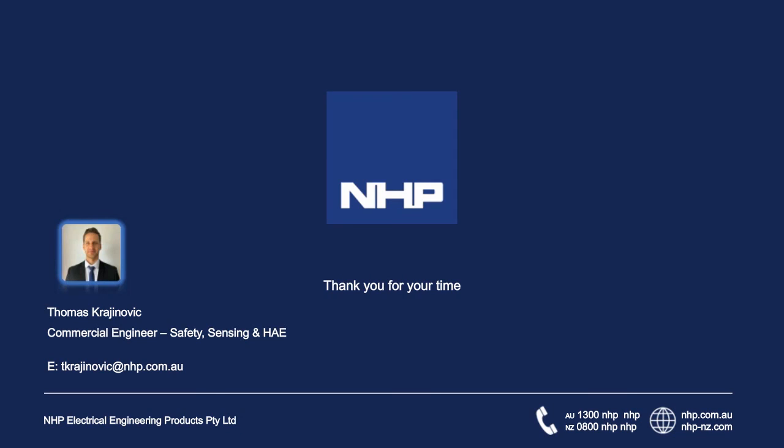Someone's asked, can I buy an unshielded sensor and block the sides so it works as a shielded sensor? What are your thoughts on that? Okay, so in that case, the answer is unfortunately no. So it's actually part of the sensor design internally, shielded versus unshielded. So placing metal on the sides of an unshielded sensor will cause triggering. Obviously, if you place something that's not metal, it won't be detected, but the magnetic field is still present there.